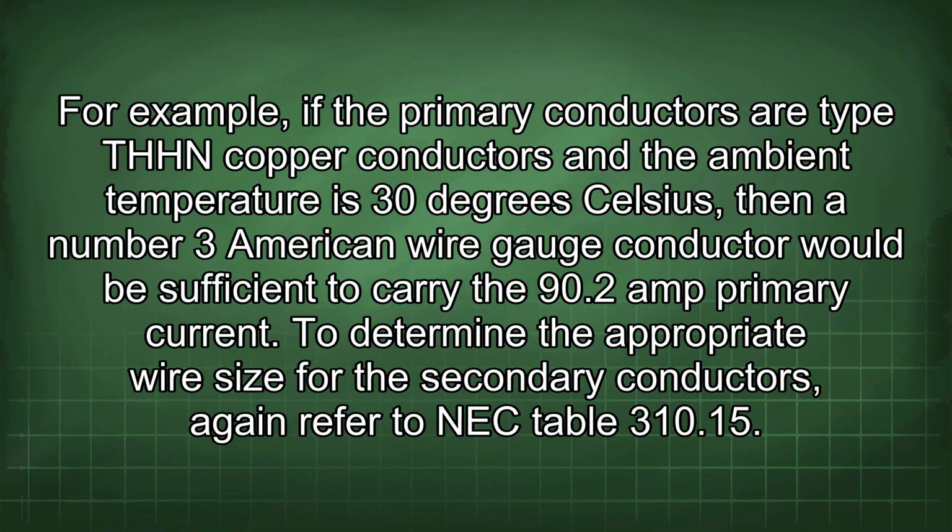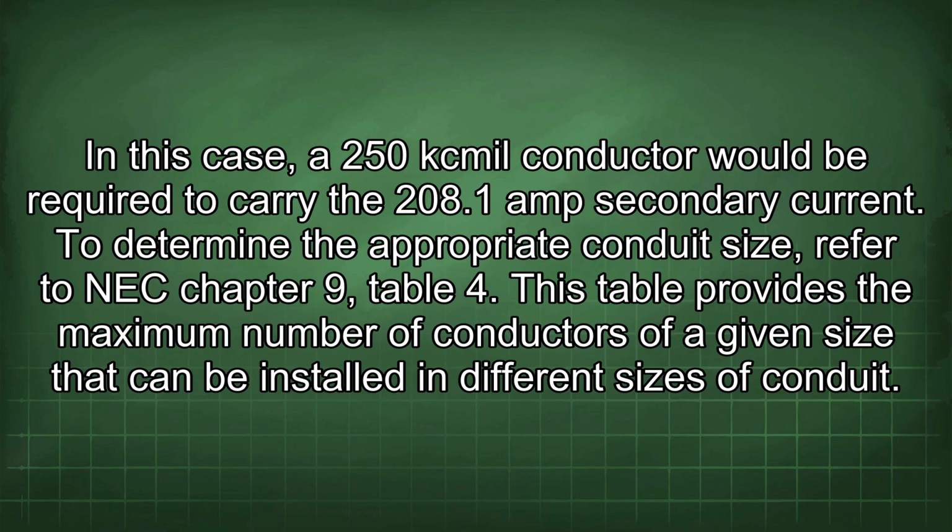To determine the appropriate wire size for the secondary conductors, again refer to NEC Table 310.15. In this case, a 250 kcmil conductor would be required to carry the 208.1 amp secondary current.